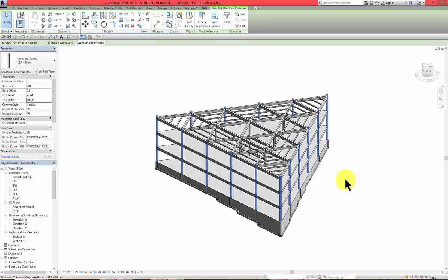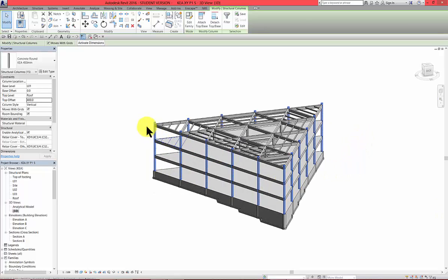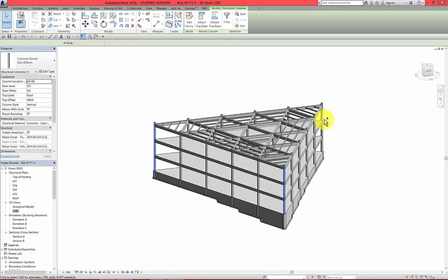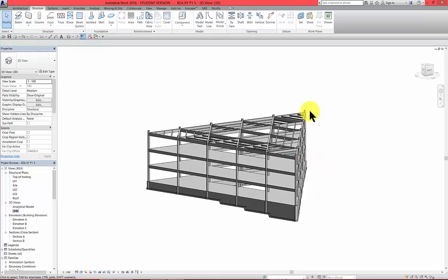It takes a while. Then all the columns around are 400 higher. The corner ones, holding Control key, select 3 of them, and then they will go 500 up. Enter. The next step is to move the beams around 400 up, and then change the corners for 500 up.